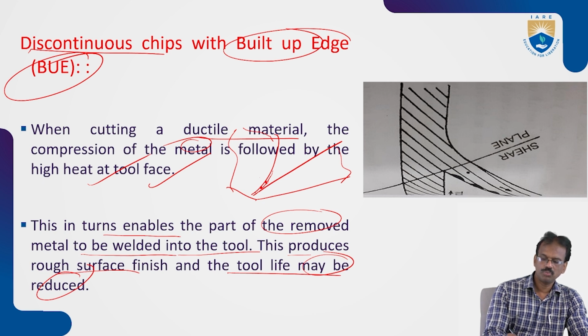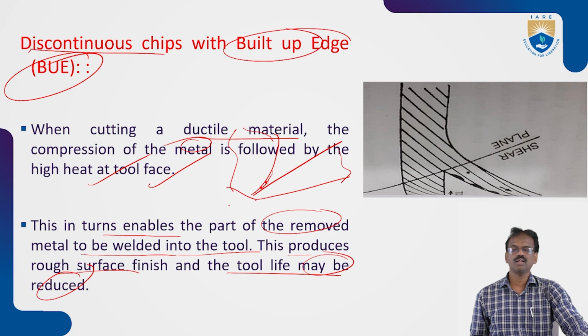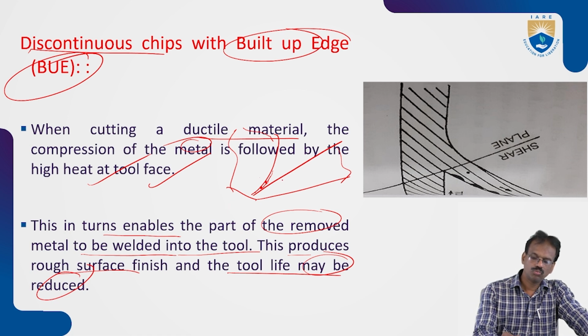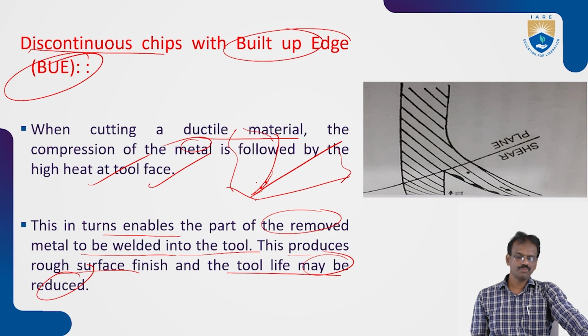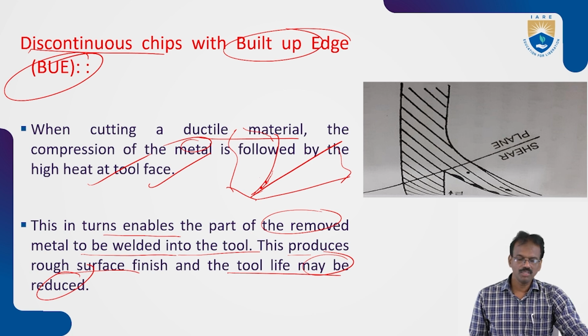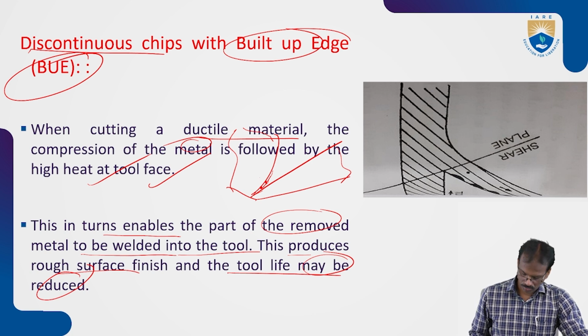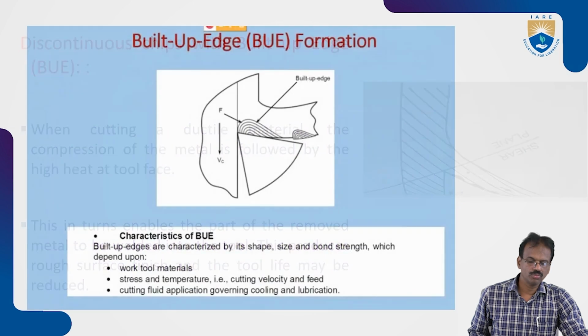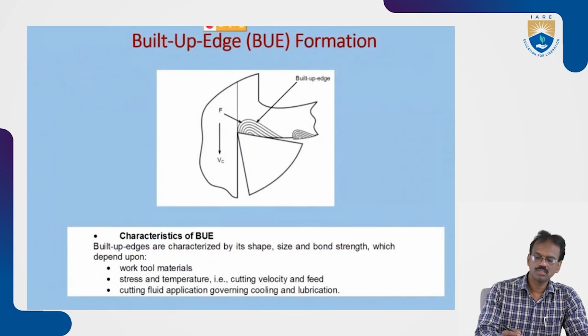So that opposes the free sliding of the chip on the tool bit. So automatically that leads to rough surface finishing also. So that is the main disadvantage of the build-up edges. You have to rectify those things also.